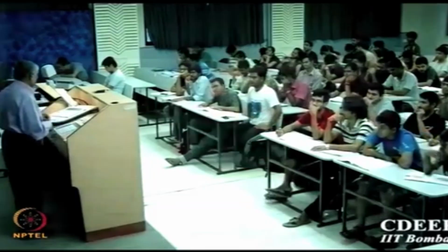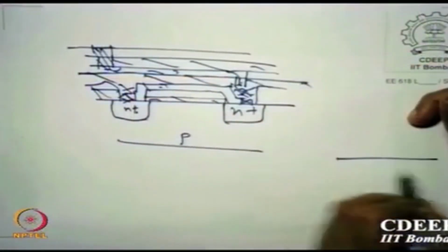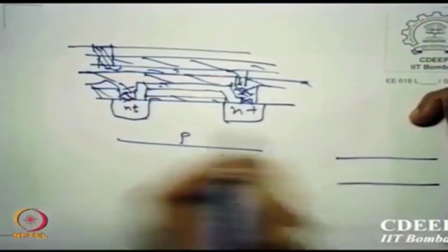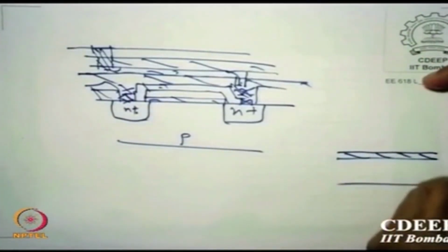In capacitors, normally between two metal layers there is an insulator. So there is a capacitor; wherever you make two contacts there will be a capacitance associated. But the way we actually do the capacitances is the following. You have this transistor process, but let us say the first poly line has been created on top for the gate, poly 1.